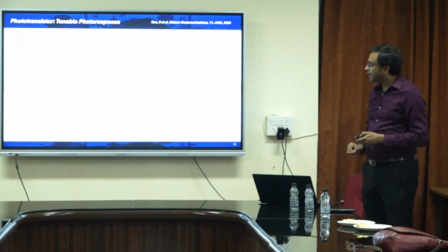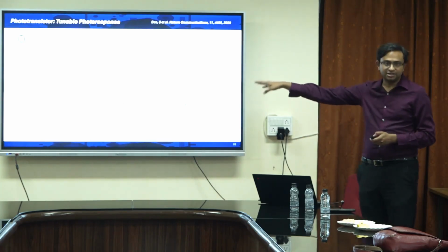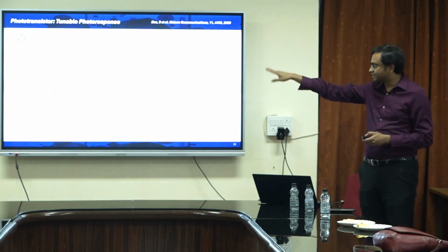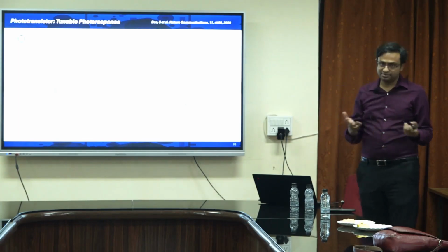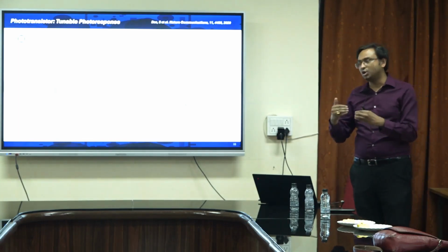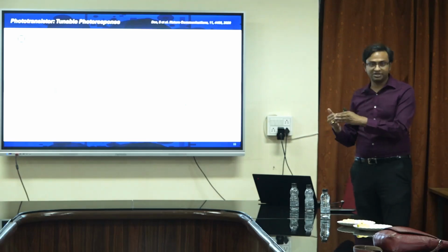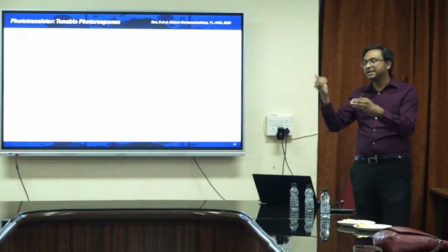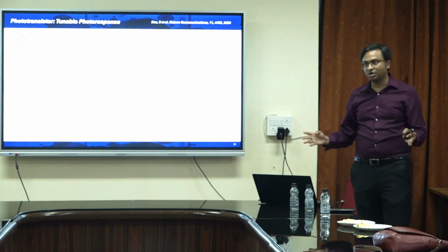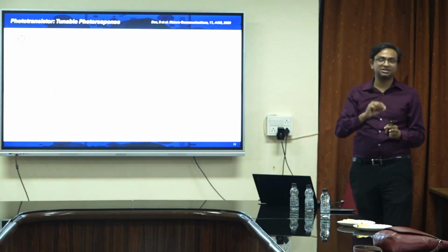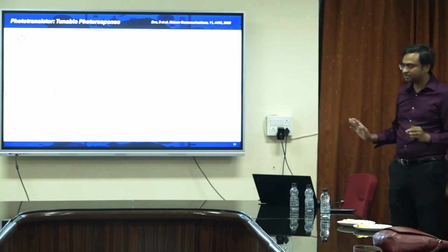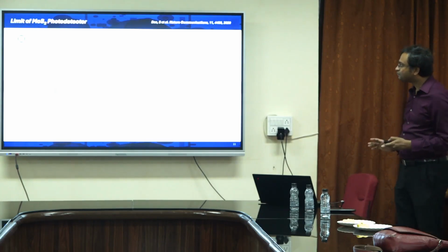And it also depends upon the intensity of the light. Like a silicon photodiode, as I changed the light intensity, the response was different, the same as for this device, right. So I did not lose anything, but I got an extra knob for controlling the photoresponse by biasing the device in different regimes, because it's a 3-terminal device. In a 2-terminal device, I cannot do it. In a 3-terminal device, I have a third terminal, which gives me this extra flexibility. Makes sense, right? This is photodetector 101.